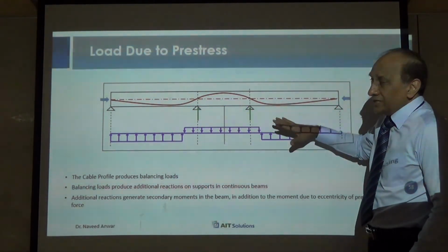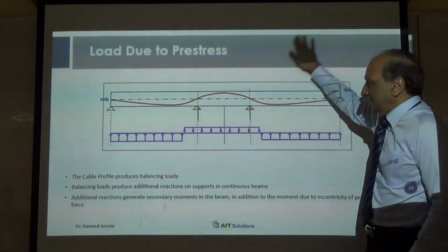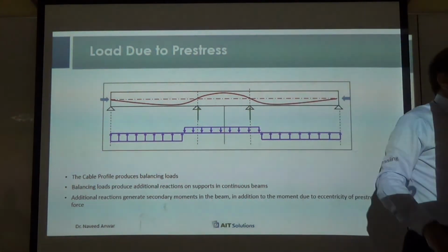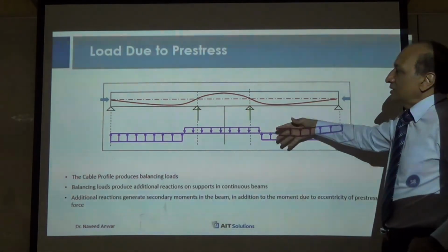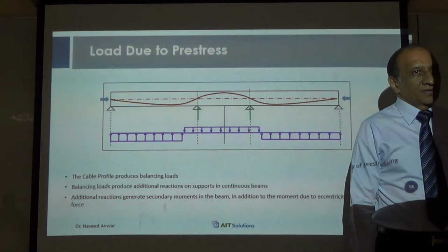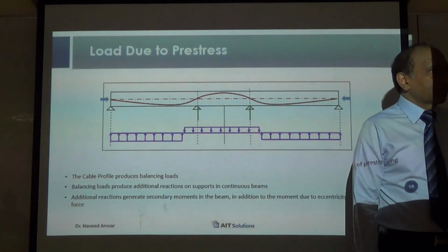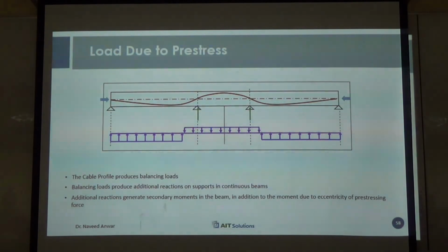So for analysis purposes, this pre-stress is converted into a load, and then the pre-stress is removed from the model. Then this pre-stressing load case is simply added and subtracted with other load cases, and that's it. As simple as that. So that's how we can handle pre-stressing in a structure.